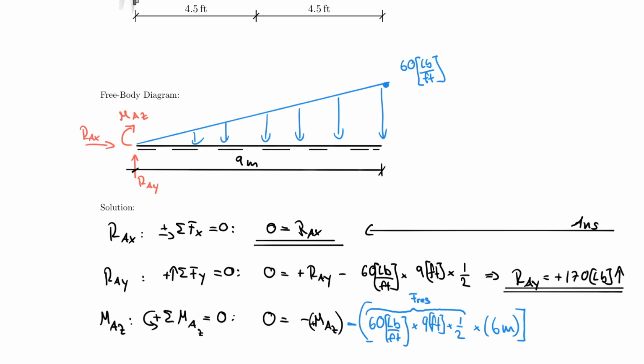Now, where did I get the 6 meters from? I'll show it to you one more time. I have a lumped force right here. This is F resultant, pointing downwards, and I know that it's 2/3 from this point, right? So this here happens to be the distance, which is 6 meters, which is really 2/3 times 9. And that's where I got the lever arm here. This is the lever. All right, and now I can solve that.